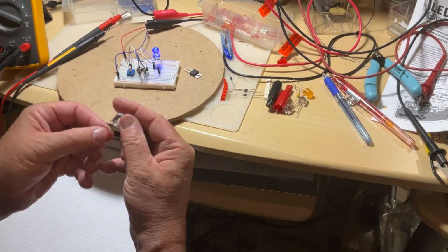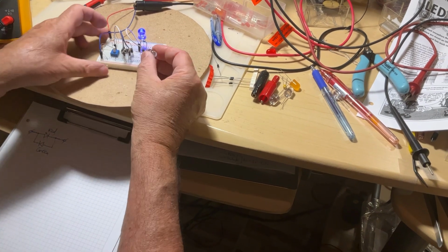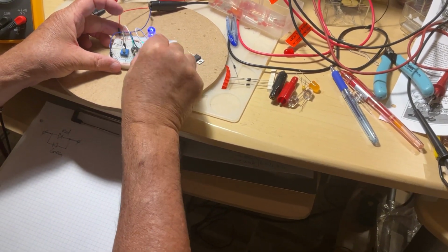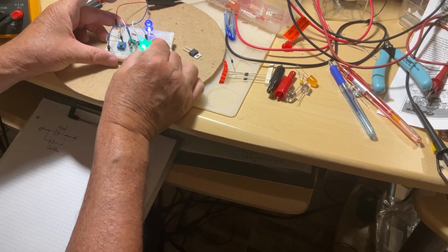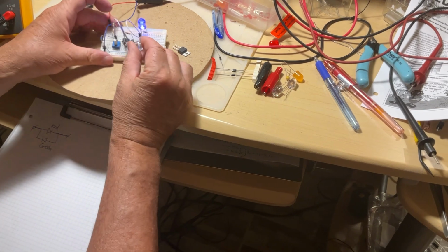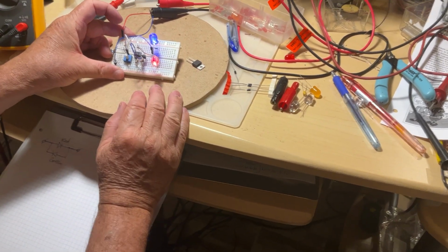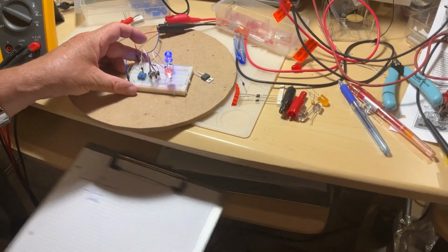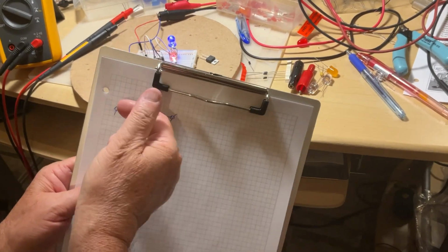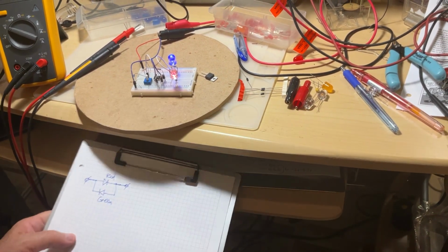Let me just find it. It may be this one. I put it one way. It's a green. I take the same diode, I just shift it 180 degrees, I put it like that. It's the red. So how come this is possible? Because they have actually 2 diodes inside the same body against each other. Okay? 2 diodes against each other. See?